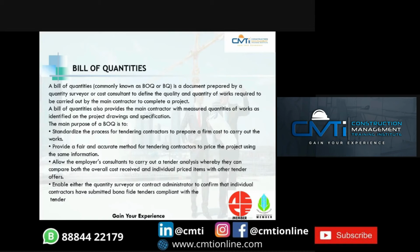A Bill of Quantities also provides the main contractor with the measured quantities of works as identified on the project drawings and specifications. So, what is the main purpose of a BOQ? The main purpose is to standardize the process for tendering contractors to prepare a firm cost to carry out the works, to provide a fair and accurate method for tendering contractors to price the project using the same information, and to allow the employer's consultants to carry out a tender analysis whereby they can compare both the overall cost received and individual priced items with other tender offers.